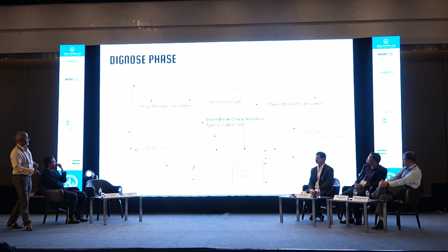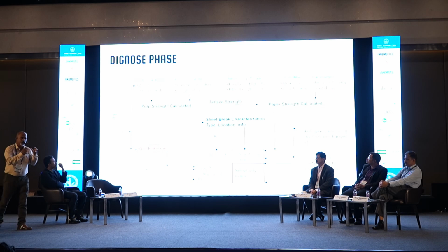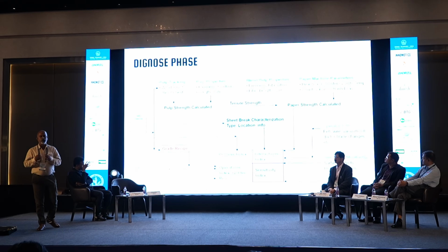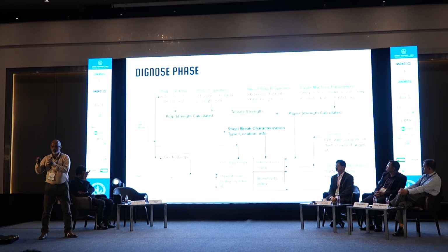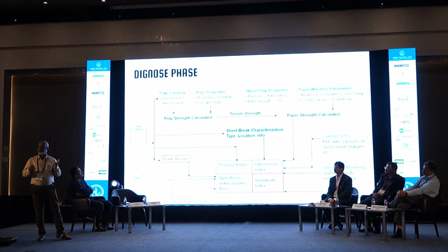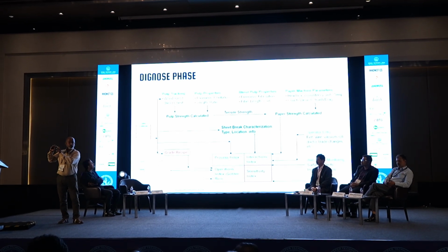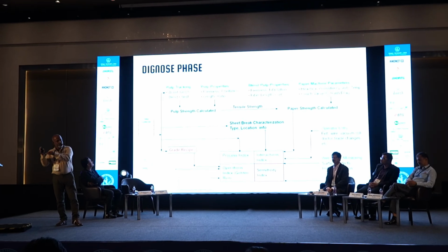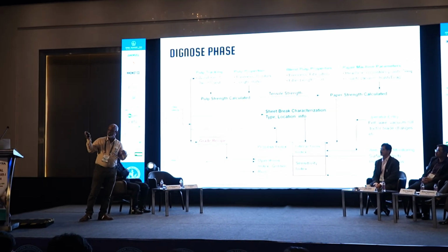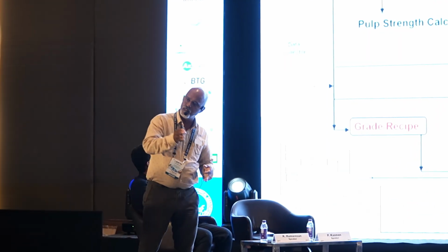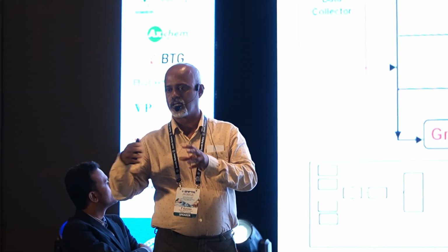Yeah. For example, before we go to the analysis, I understand from the pulp mill what type of pulp we are making. In the pulp mill, we have a hash factor or kappa number, whatever you call it. We have a lot of data available in the pulp mill. We track how it is coming to the digester, what is the current condition of that digester, and then we move to washing and bleaching, and then we have storage in the paper machine, and then I quickly go to the refiners.